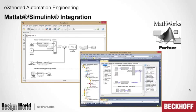And so there is a mechanism in Simulink to say, go ahead and create a TwinCAT module, or excuse me, a Visual Studio module. We bring it into Visual Studio, run it in our kernel. Better than that, as you see on the screen, we can actually poke in and look at the values online and even write the values. And that's never been possible. And that's been a big hit because, again, debugging and manipulating and simulating becomes simple. It's amazing.